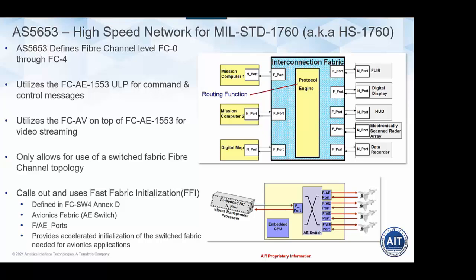We'll definitely talk about this more in one of the subsequent follow-on webinars, but at a high level, what's going on with FFI and NXD is that an avionics environment contrasts with a traditional Fibre Channel, land-based, lab, datacom type of application, where you can have a very dynamically configured network. In avionics, you want the network to be very statically configured, and you also need it to be operational very quickly after a reset or at power on. That's primarily what fast fabric initialization provides.